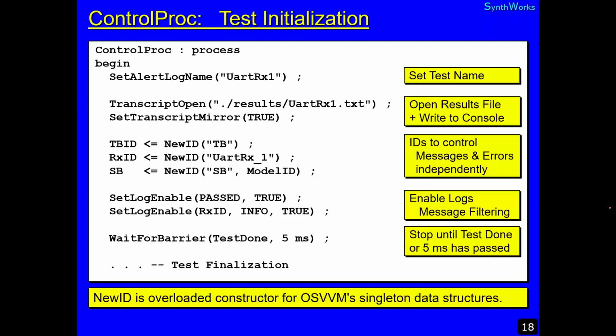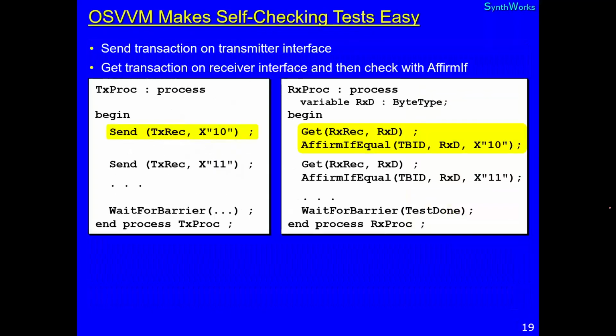Right now, most vendors allow you to do it in a declaration anyway, although technically doing that is illegal, so I'm never going to show it in my presentations and not going to have it done that way in any of the released OSVVM verification components. We'll do it the harder way until the language says it's legal, because OSVVM is intended to be strictly VHDL legal.